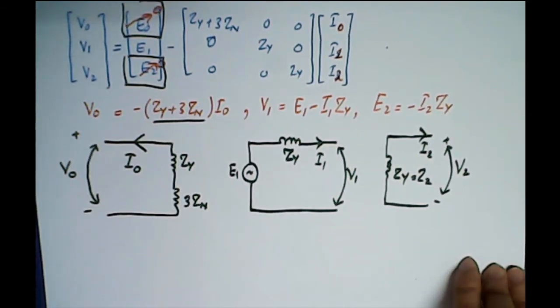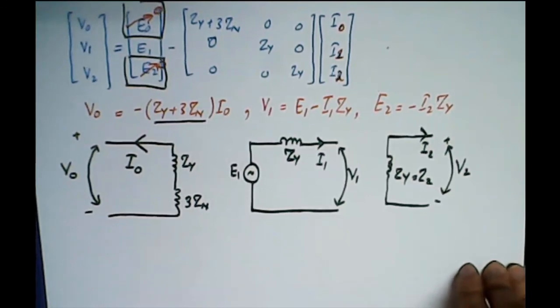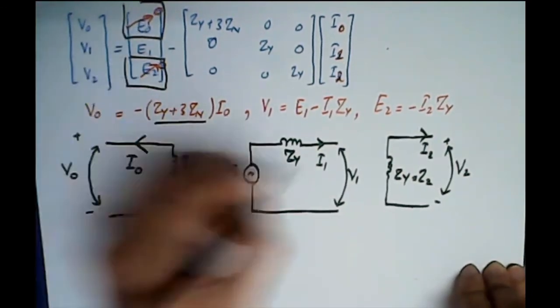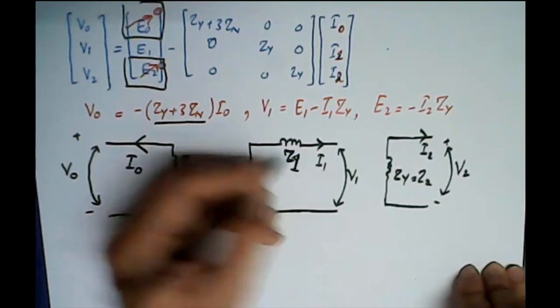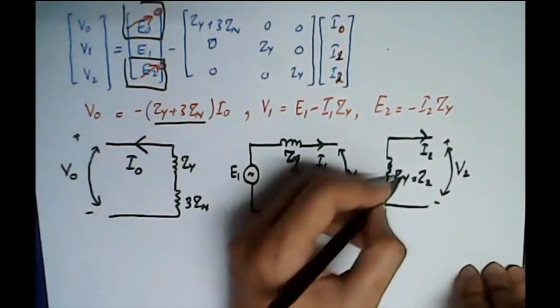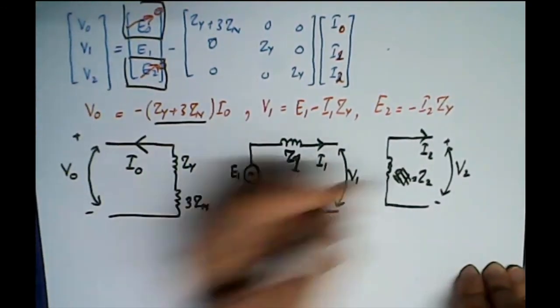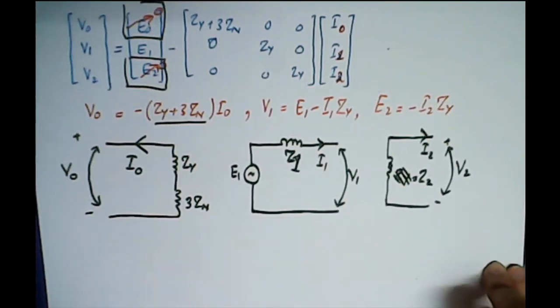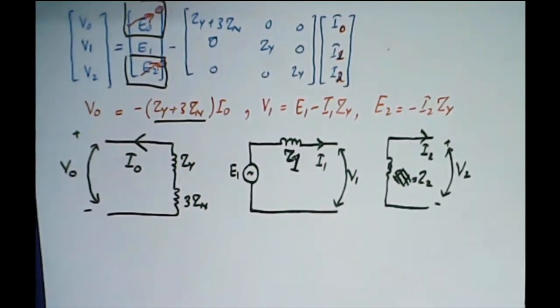The same, right? And that is why we say the zero and negative sequence voltages are 0. This is Z1, Z2. Practically these are not all equal. Z1 is more and Z2 can be the same, but Z0 is different, right? Why? Because of the neutral impedance.